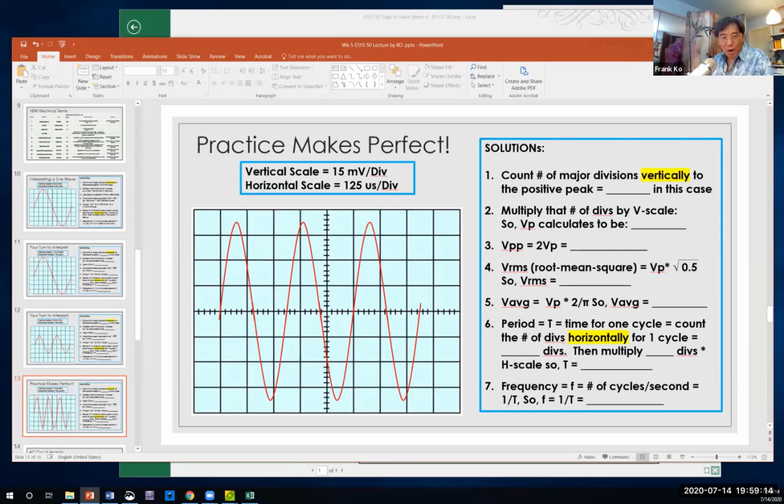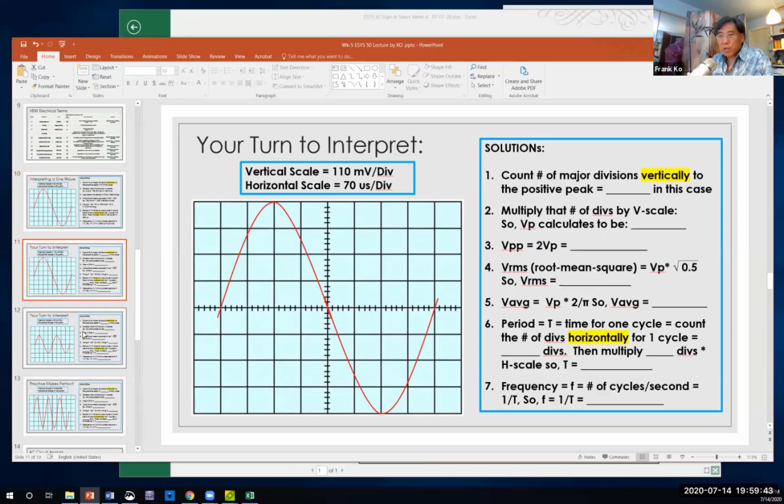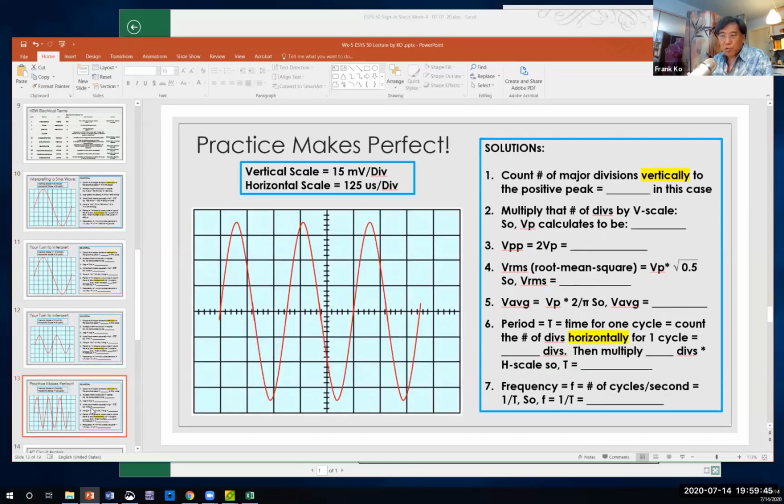All right, the process is correct. We take the period of 312.5 microseconds, which we calculated a moment ago, hit the reciprocal key, hit equals, and the display of your calculator should show 3.2 kilohertz. Is everybody okay with 3.2 kilohertz? Thumbs up. Any questions on any of these 4 waveforms that we have just played with? The most interesting of which happens to be this one.